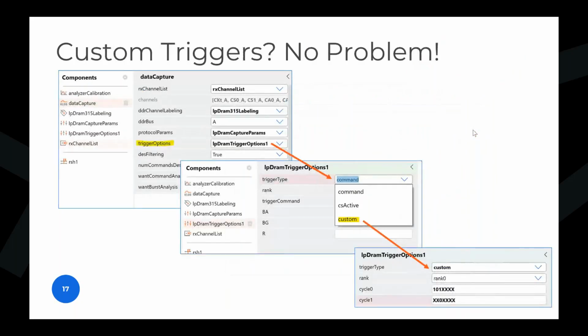And then, of course, being an analyzer, you need to trigger on commands. So this particular tool basically decodes the CA bus and the chip select signals in hardware. And what that does is it allows us basically to trigger on specific commands, or to even create custom commands. So in any Introspect analyzer, whether it's for DDR or other applications like MIPI or DisplayPort, what we always have is a real state machine, like listening to the traffic that's coming in, and a data capture that we display in the viewer is really nothing but just a frozen snapshot of the traffic in time, right?